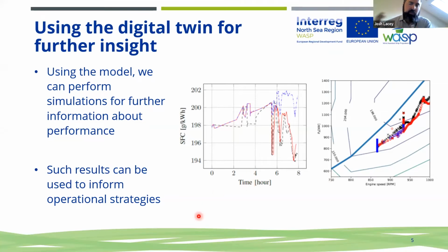And so once we have the digital twin validated using real world data from sea trials or experiments at the industrial scale, and we have all of the technical specifications, so we have the specific digital twin built that represents the physical asset, then we can start to gain deeper insight, and we can start to feed back into the physical asset to say, if we're at this condition, perhaps we want to adjust the propeller pitch based on this amount of wind thrust that's available, or maybe we want to downspeed or depower the engine, something to that effect. That's the idea, being able to feed back in real time or near real time a control strategy to try and improve operation and performance.